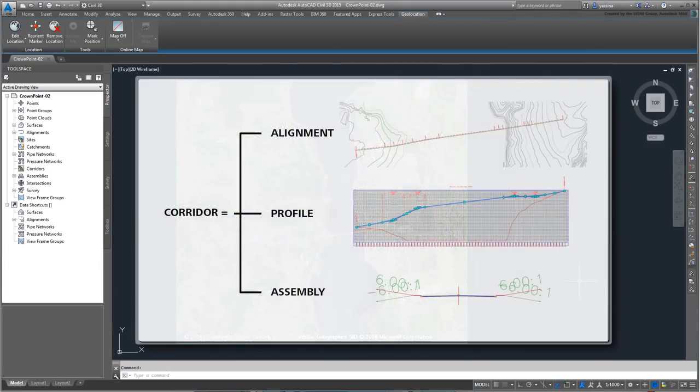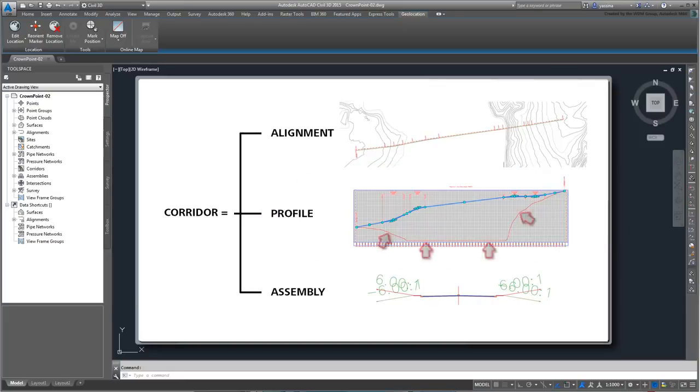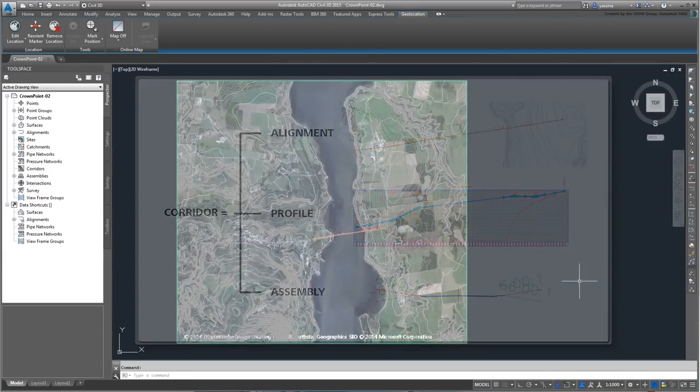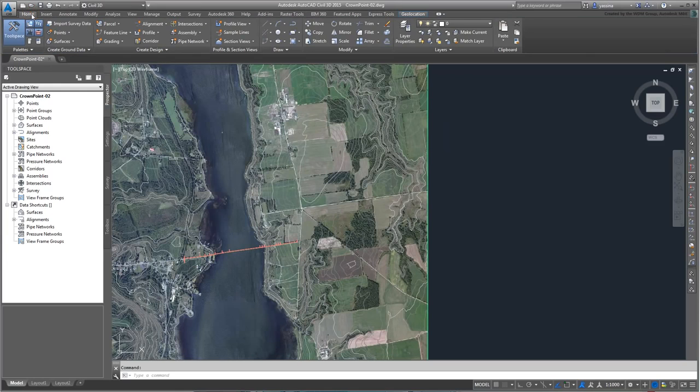A profile is a side projection, or a cross-section of the terrain, if you will, along a given alignment. It will let you view the topography of the terrain, and as such lets you build a profile of your road in relation to the terrain. To create a surface profile, first make sure you are in the Home tab. Under Profile, choose Create Surface Profile.